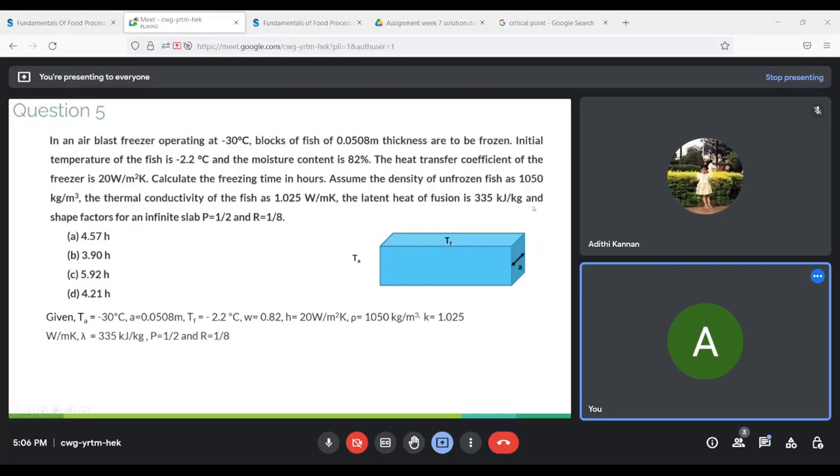So your heat has to transfer all the way to the inside of your slab. Since the inside of the slab is a solid, we deal with conduction. So from the middle of the slab to the surface you involve conduction, and from the surface of the slab to the surrounding air, you involve convection, which is why you have both h and k involved in this particular problem.